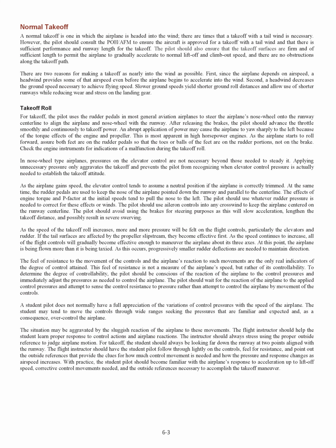A student pilot does not normally have a full appreciation of the variations of control pressures with the speed of the airplane. The student may tend to move the controls through wide ranges seeking the pressures that are familiar and expected and, as a consequence, over-control the airplane. The situation may be aggravated by the sluggish reaction of the airplane to these movements. The flight instructor should help the student learn proper response to control actions and airplane reactions.